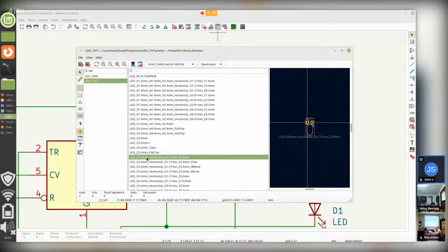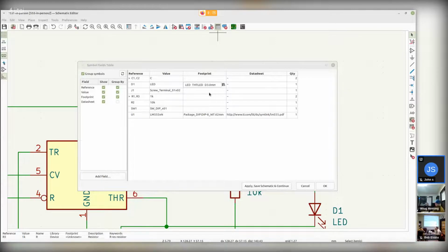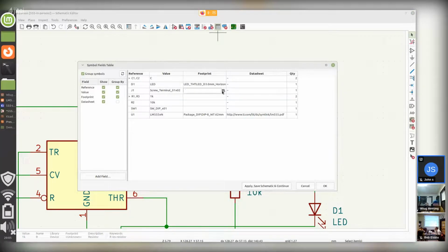To the edge of the board. Here's a thing about the software that's a little not intuitive. You'd expect that there's an OK button here. It isn't. You have to just double click on that. It took me a minute to be like, where's the OK? Because everything else is OK. Oh, it's just a double click on it.